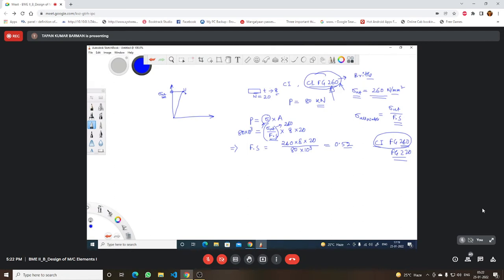But when taking that material in our design calculation, that is my tensile strength value. Using the tensile strength value, I have to apply the concept of factor of safety to get the allowable stress or design stress or working stress. Now the point is clear to you.